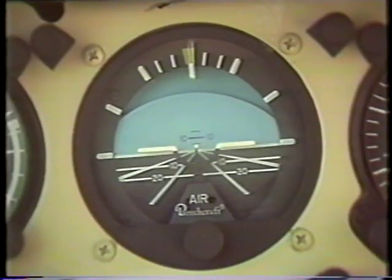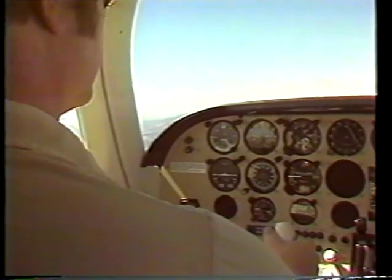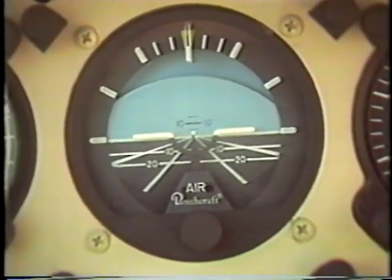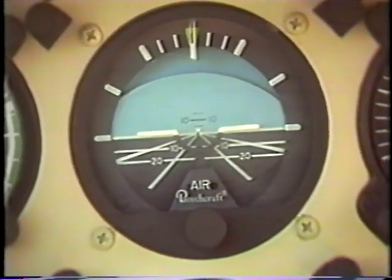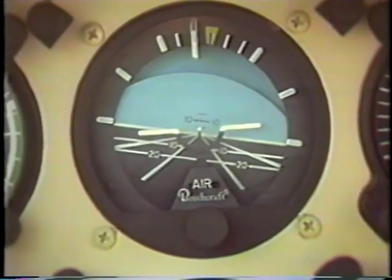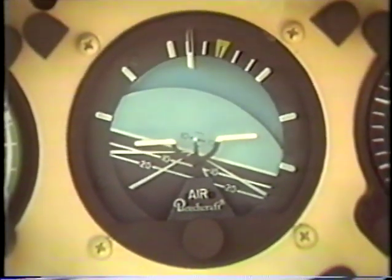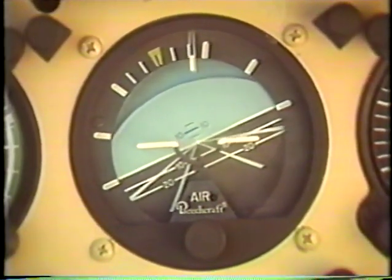The attitude indicator is also referred to as the artificial horizon or gyro horizon. Most attitude indicators on light airplanes, like the Skipper, are air-driven. The attitude indicator provides the pilot with a visual picture of the airplane's pitch and bank attitude with respect to the horizon. It consists of an airplane silhouette fixed to the face of the instrument and therefore aligned with the airplane itself, and a graphic representation of the horizon which is attached to the gyro.